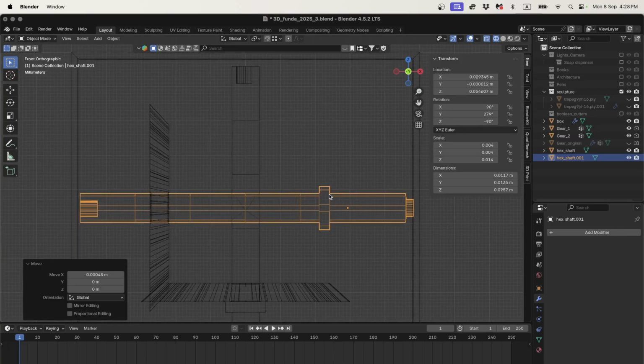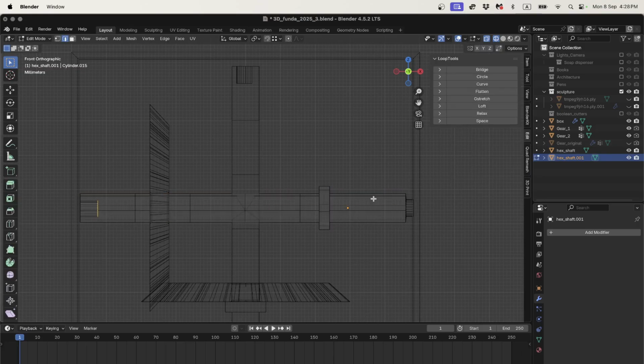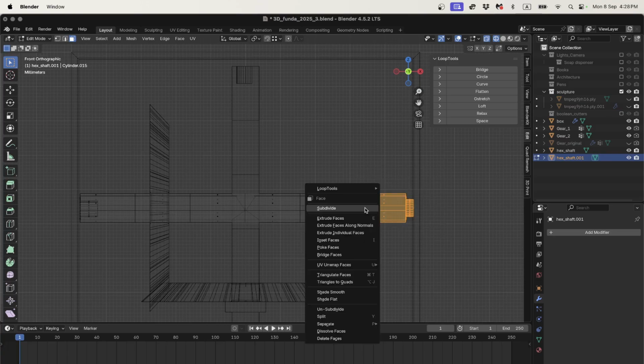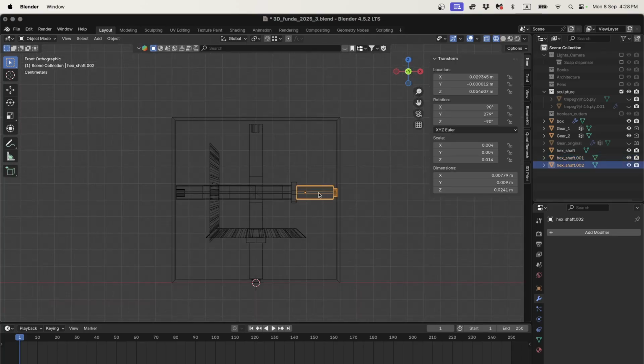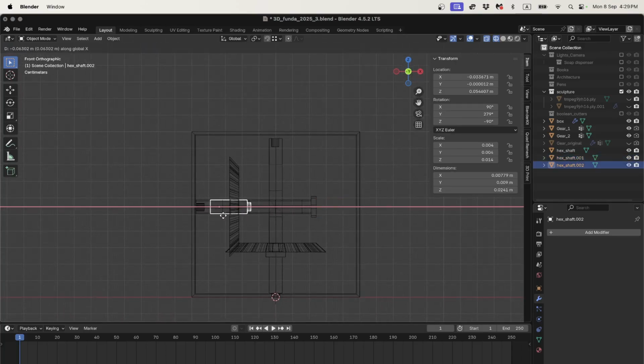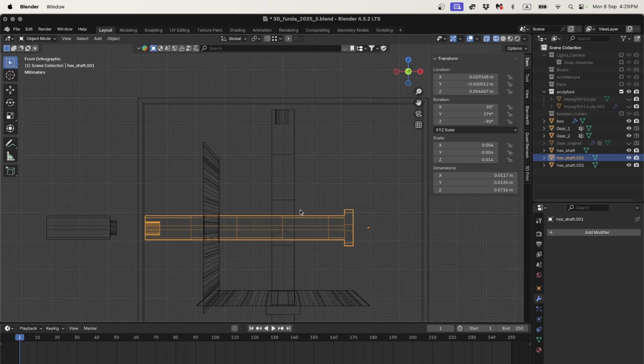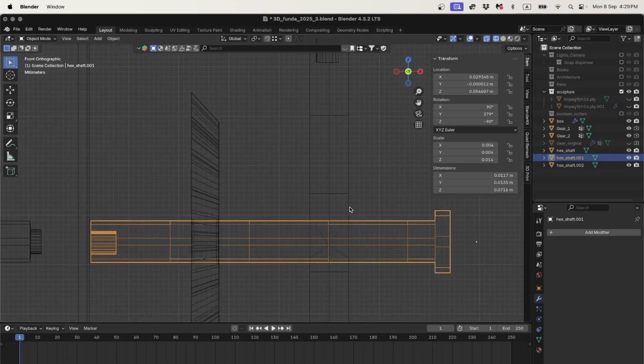I think this part is sort of like what the outside of our shaft is going to be. So what we could even do is, I don't know if we'll use it, but we can just grab this, and a cool thing we can do is right click and say separate selection. So now that's a different object. So I can just press GX, pop that over here,